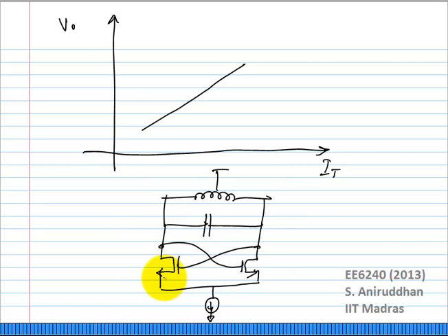Okay. First of all, the output is biased at VDD. Correct? So obviously when the VCO swings, it is going to swing above VDD and below VDD. Right? How much will it swing above VDD? It will swing as much above VDD as it swings below VDD, right? So as you keep increasing current, the amplitude will keep increasing above VDD also, right?